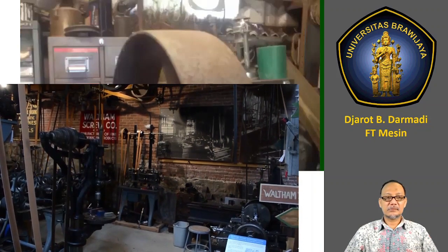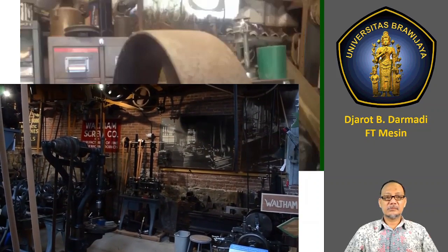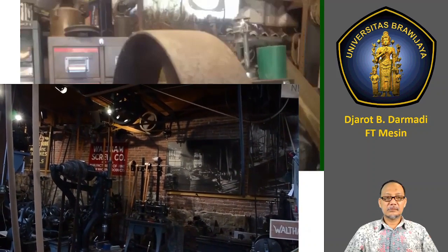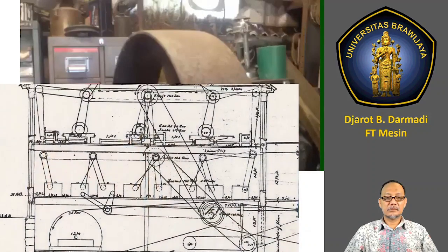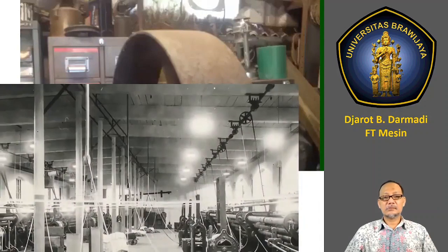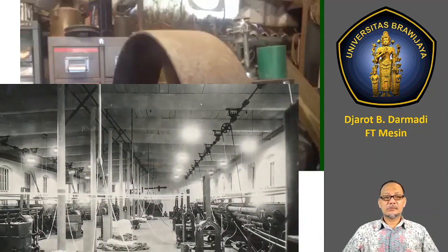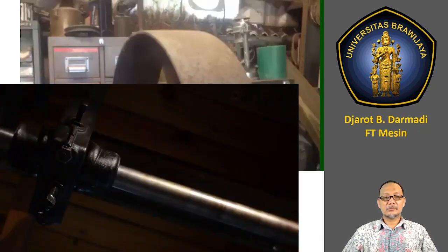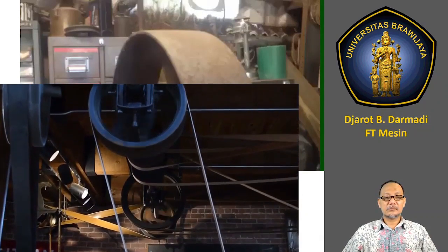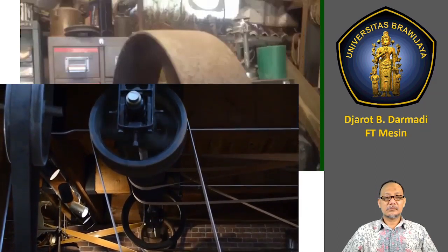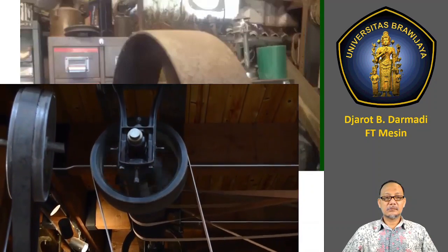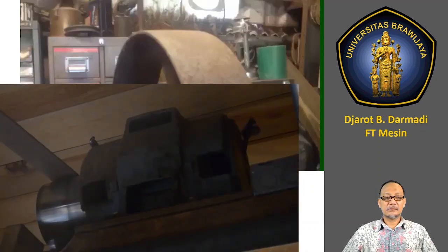The driving force behind heavy industry is the practical transmission of motive power. Prior to the development of compact electric motors, the belt and line shaft system was used to distribute power from source to machinery in most industrial workshops and factories. The system is comprised of 3 basic elements: shafts, pulleys, and belts. Central power would be derived from a machine generating rotary motion such as a steam engine, a turbine, or a water wheel. In the case of our machine shop, power is supplied via an electric motor.